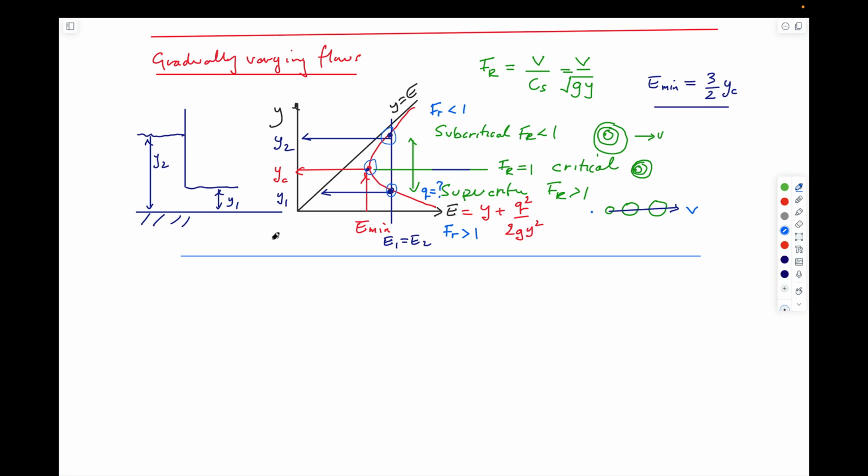And indeed on everywhere you see this. And so if you constrain the flow to be at a particular depth, either unconstrained, which would be this, or constrained maybe by an undershot sluice, then the flow here would have to be flowing at this particular point. It could choose any of these, but the geometry of flow might constrain it to be in one particular one. If you wanted to move as you go downstream from this point to this point, and you have the same flow rate, then you physically have to move through this nose. And so you have to put a constriction in here that will allow you to get through at this particular magnitude at a Froude number equal to 1. And so that allows you to look at gradually varying flows.